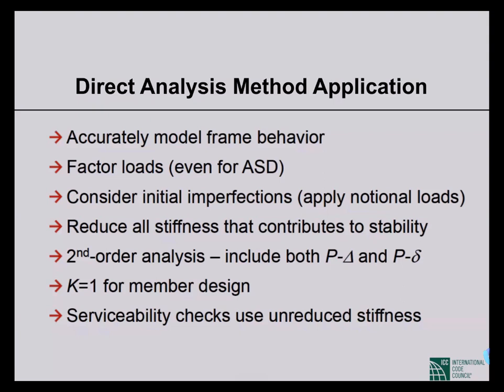And the last point is that for serviceability checks, we have to use unreduced stiffness. So we have to run our models many times. I'll explain why we have to do that. For serviceability checks, we cannot reduce the stiffnesses. So we run with unreduced stiffness values and check the serviceability limit checks. So these are some important points that we have to remember while applying direct analysis method.